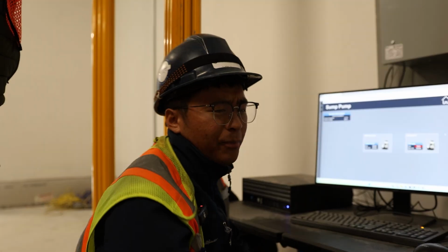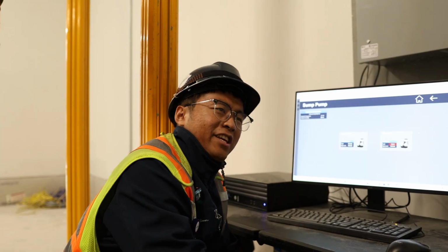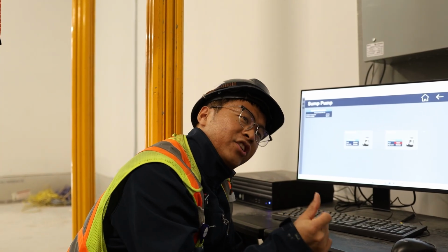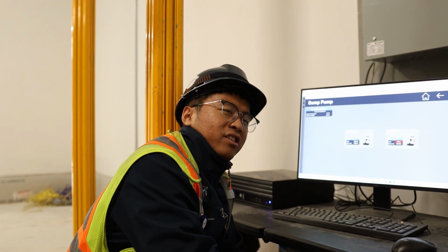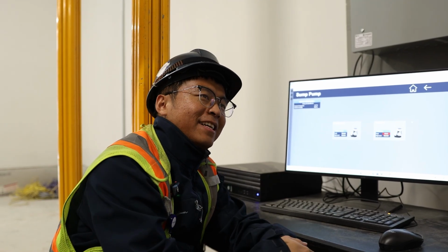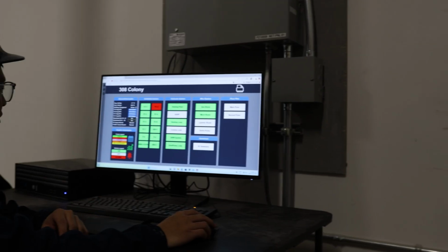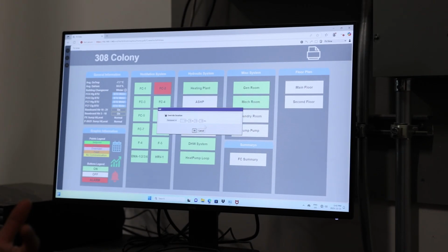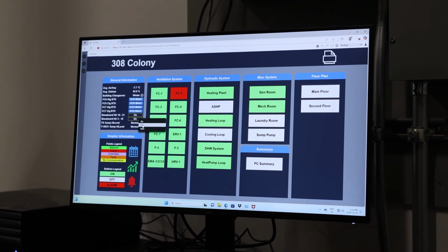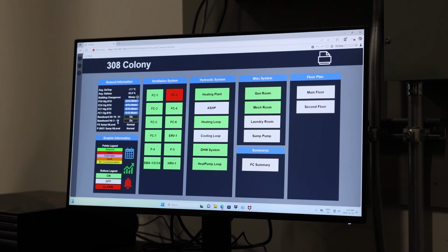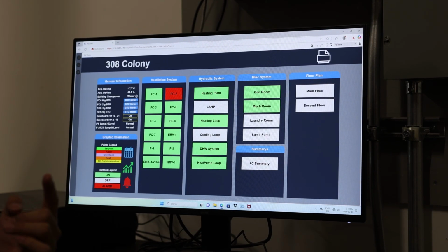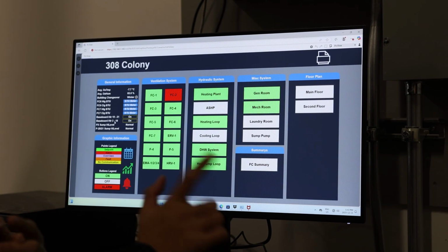It's just based on the building mode. If it's in heating mode, it turns on. Cooling mode, it turns off. The BMS will only turn it on or turn it off. That's it. So you can just turn it off or turn it on with the basic word. From 3rd floor to 18th floor, that's one command. From 19th floor to 21st floor, that's another command.